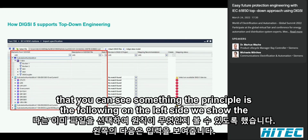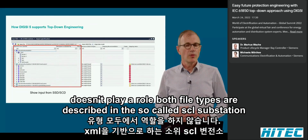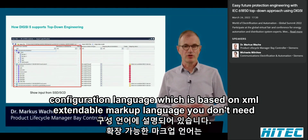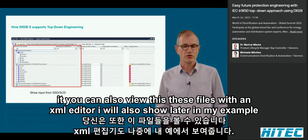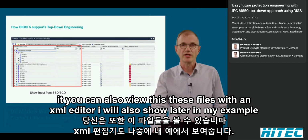On the left side, we show the input. It's a sort of requirements list. The input from this SSD or SCD file. The extension doesn't play a role. Both file types are described in the so-called SCL, Substation Configuration Language, which is based on XML, Extendable Markup Language. You don't need to remember that, it's not so important, but for those who know this, it may be interesting. You can also view these files with an XML editor. I will also show it later in my example.